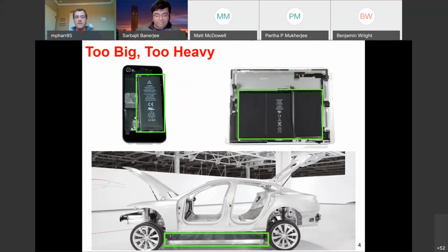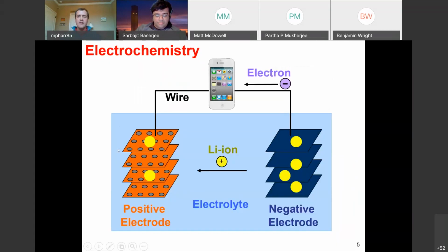And so the emphasis of this talk is going to be looking at some candidate high capacity systems and looking at mechanical issues in those systems and hopefully how we can mitigate that. Our approach is to do basic characterization of the mechanical properties of these new materials, or at least they're new in the sense that you start with some material, you put lithium into it, and it evolves continuously in its properties while you're electrochemically cycling. We look at damage that occurs in these systems, and then try to come up with ways to hopefully mitigate some of these mechanical issues. And so Matt's sort of given an overview of this.